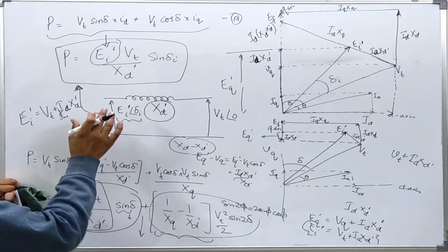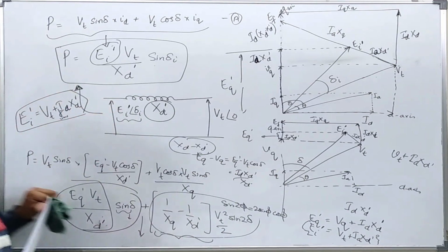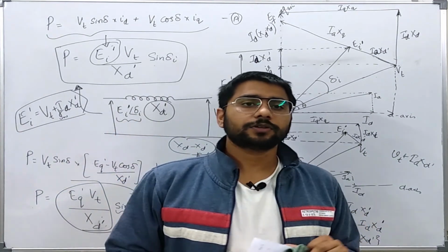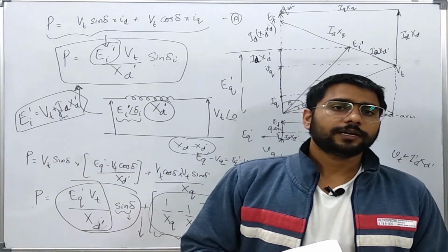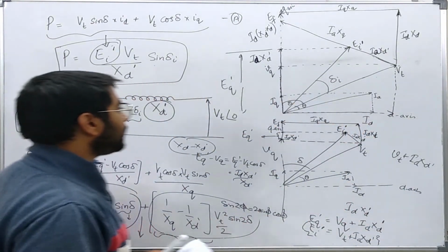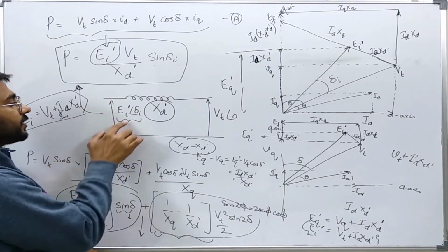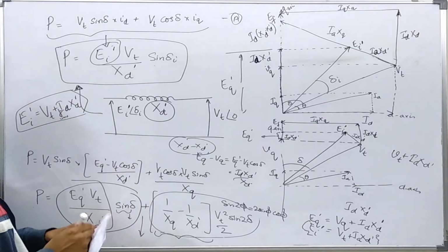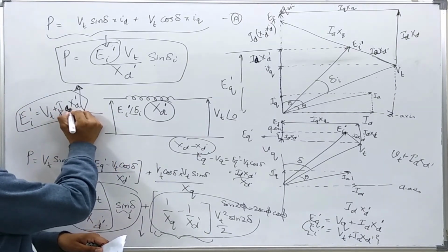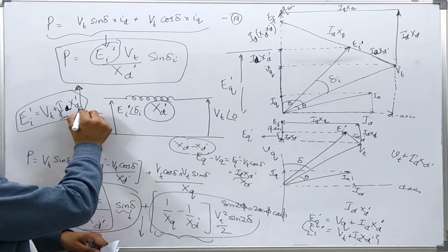So you see that the equivalent circuit model for a synchronous generator which was having some load initially and then went to a symmetrical fault is a model in which this is the voltage source, whose value is dependent upon the load current IA flowing initially before the fault happened, and the transient reactance.